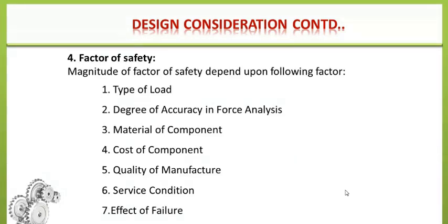Then effect of failure. Now, effect of failure is very important. Let's say, what is the effect after failure of a mechanical component? Let's say bearing failure in a gearbox. What is the effect? The gearbox stops working. You have to open the gearbox and replace that bearing. This is the only work that you require, plus the bearing cost and opening expenses. But what about the failure of a safety valve in a pressure vessel? In industry, it may create a blast of that pressure vessel. There may be a very hazardous condition, or it may affect the life of workers there.